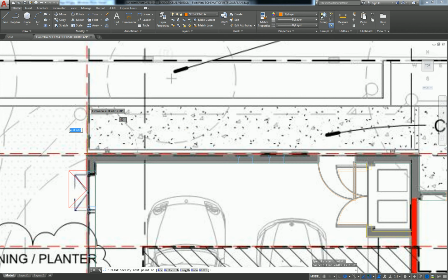And when you're drawing your values here, pull your cursor up to approximately where it ends and then type in the rounded figure. That's probably the easiest way to get an accurate number, because you don't want to see like 5/8 or 113/256ths. That's just a ridiculous number, and it gets really messy in Revit when you have these unclear figures.